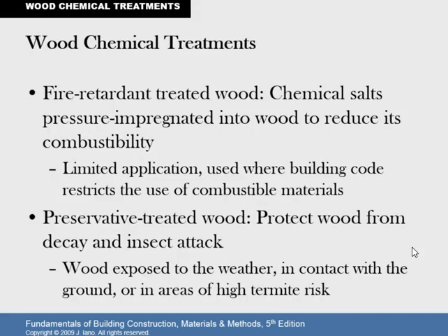Okay, wood chemical treatment. So there are 2 different reasons to treat different timbers. First, fire retardant treated wood. So chemical salts are pressure impregnated into the wood to reduce its combustibility. This is used where building codes restrict the use of combustible materials. It's not very common to come across fire retardant treated wood in general.